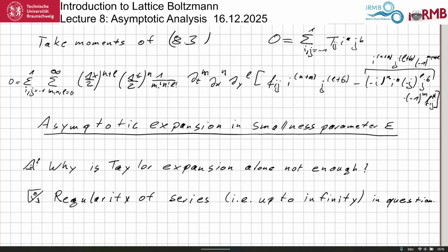I have not shown this for 10 years or so, but what I've shown previously is also when you have these oscillating results, especially with the lid-driven cavity problem. You can choose a resolution where you have very high frequency noise, in particular in the pressure in the second moments.